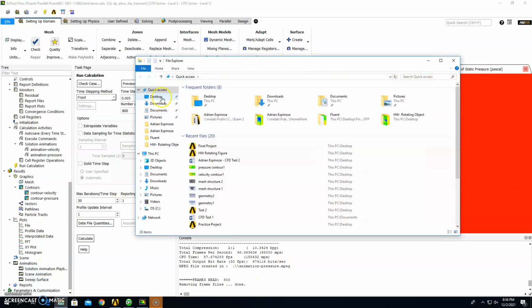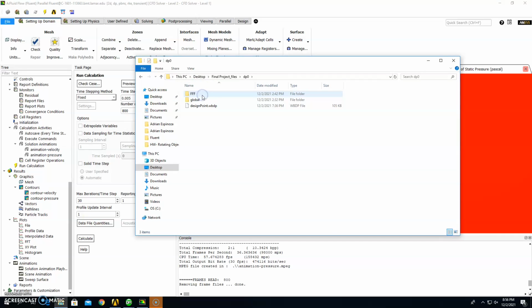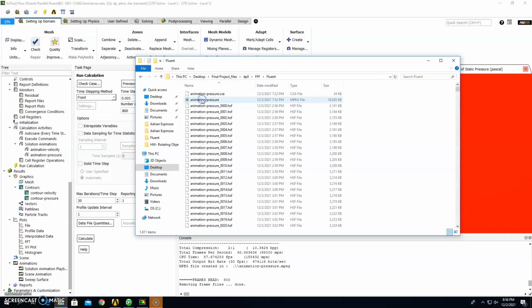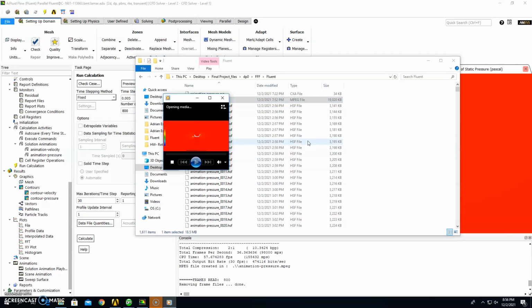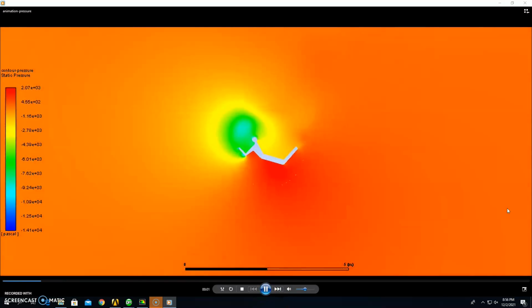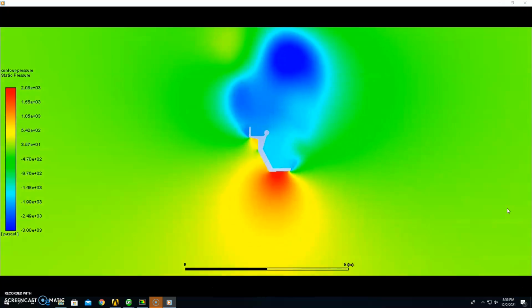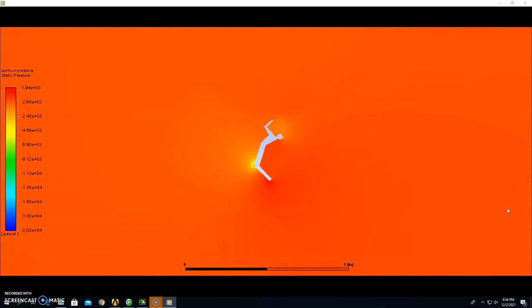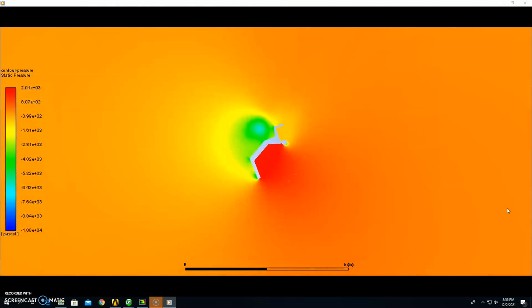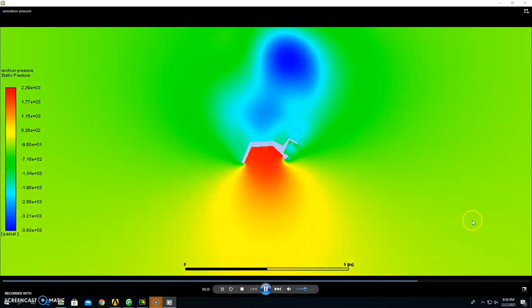Once both animations were written, we checked the file under which the project was saved. You open the file into DP0 FFF Fluent, and here you can find the animations for pressure and velocity. Here the pressure, we opened it with Windows Media Player. Here you can see the static pressure as the Skydiver rotates. Through this animation we can see that the static pressure is highest where the air directly pushes against the Skydiver, since the air is rushing from the bottom upwards.